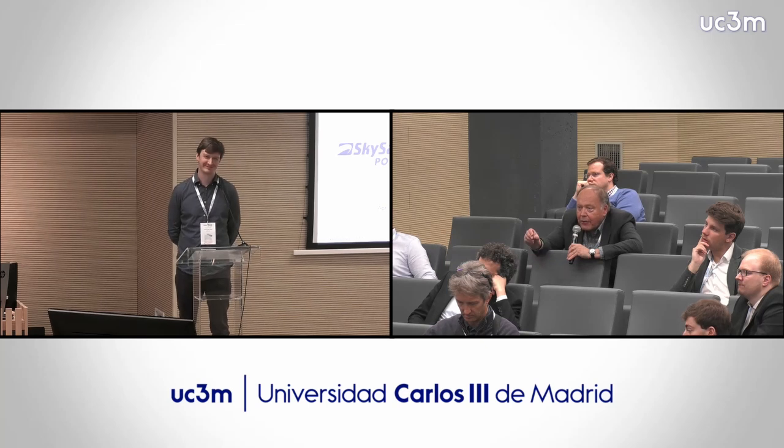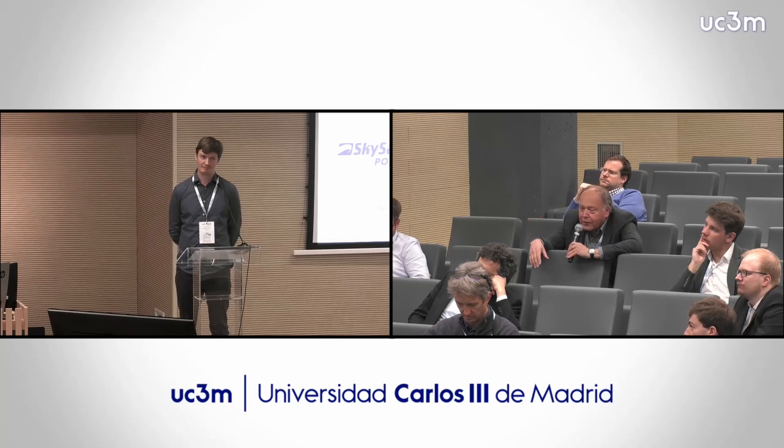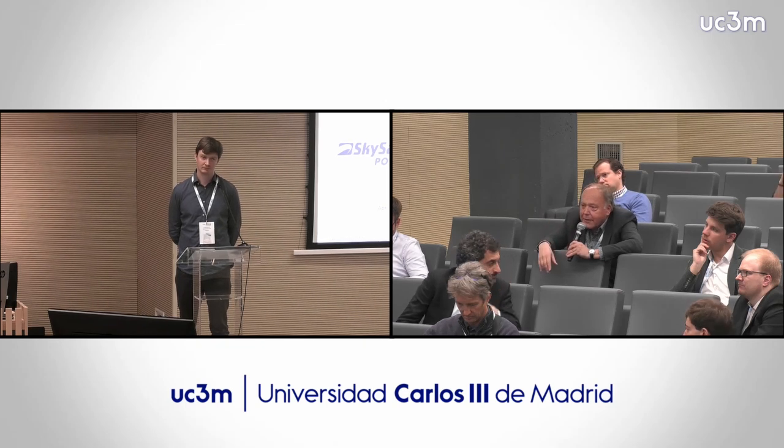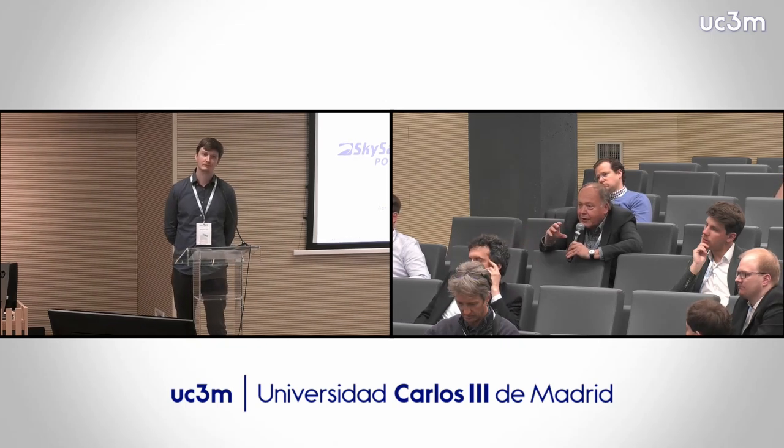And then I was thinking that maybe you could model the flow in the intakes, because these are basically pipes, right? You could model them in a simple model. I don't know how to do it, but you could maybe couple the panel method simulation with the simulation of a turbulent flow in a pipe, on which you can do an analytical model of the head losses as a function of the distance. This is a turbulent flow in a channel, in a way.